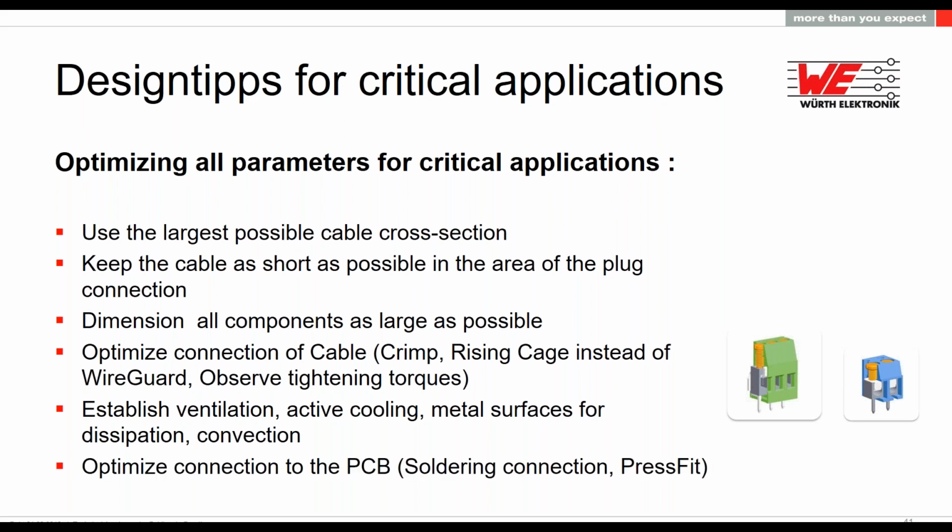And finally, of course, you can sometimes also optimize the connection to the PCB. If soldering is probably having too much contact resistance and you create too much heat because you really need a lot of current, then you can also change to press fit solutions, for example, that have much lower contact resistance towards the PCB, and with that spread less heat.